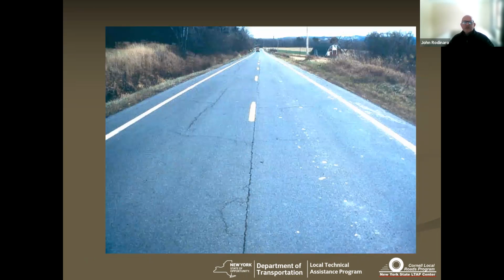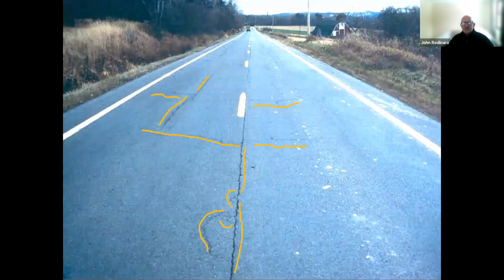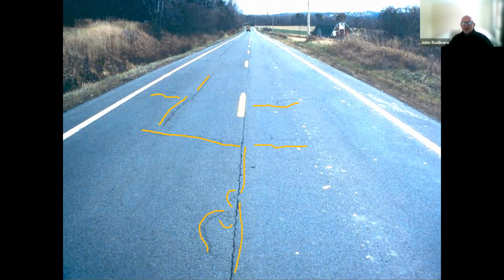And wanted to look at this. This is another typical example of what we'd see out in the field. And we want to just go through a quick exercise to show you how you can start to visualize how much material you're going to be placing on the pavement. So you start with your picture, take it back to the office, hit it with your markup tool, with the pen, and you can quickly visualize how much repair material you're going to be placing on those cracks. In this case, it looks like this is a fairly low density cracking, mostly along the center line.